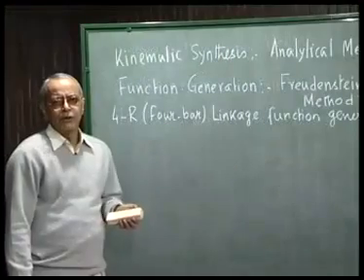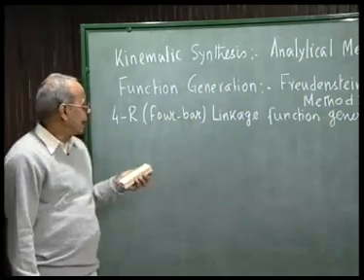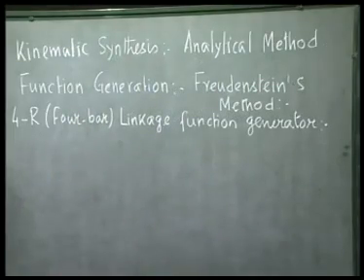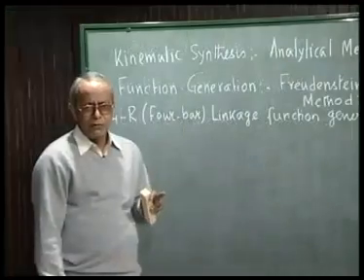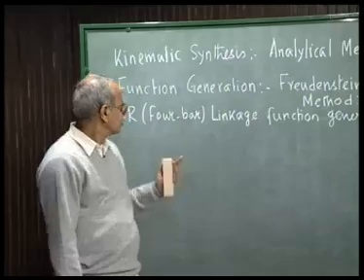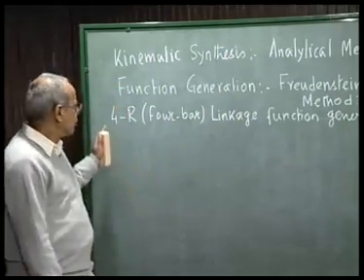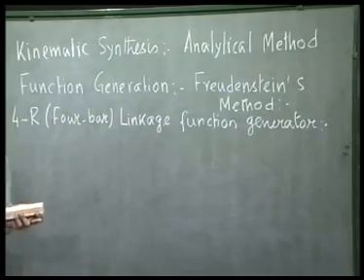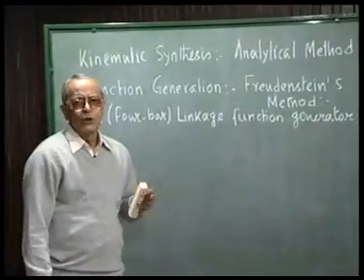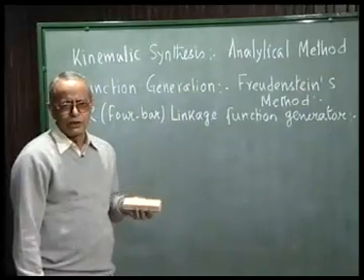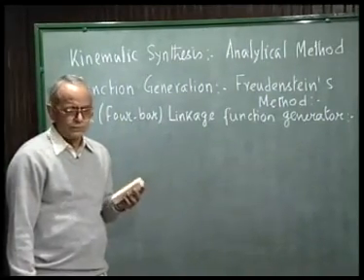If we remember, when we discussed graphical methods, we had function generator for 3-position synthesis and 4-position synthesis. However, we shall restrict ourselves only to 3-position synthesis so far as 4R linkage function generator is concerned. As we shall see later, for 3-position synthesis, we can get away by considering only linear algebraic equations, which are very easy to solve.